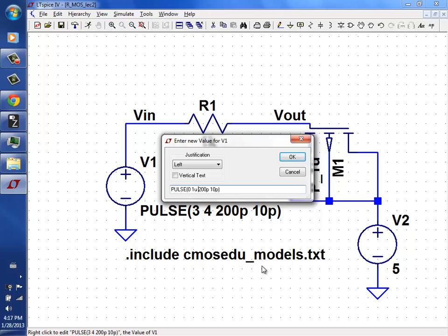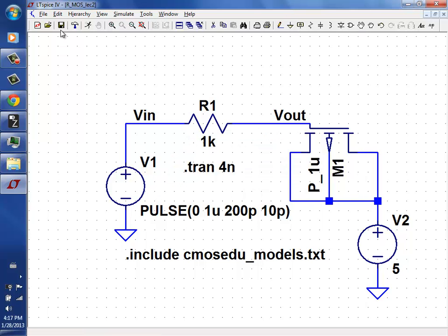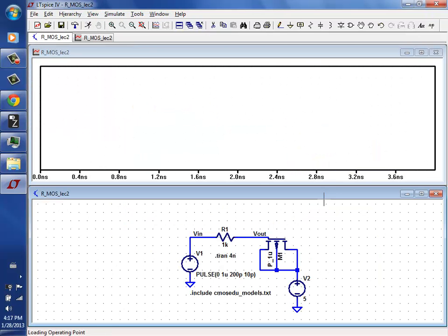Now, just out of curiosity, this is a PMOS device. What we had before was an NMOS device. How do we expect the capacitance of the two to change between PMOS and NMOS? It shouldn't. It should be exactly the same because we have exactly the same oxide thickness. Where we get confused is when we talk about mobility and IV characteristics and all that, but the capacitance is exactly the same. So let's go ahead and poke the running man and go over here.